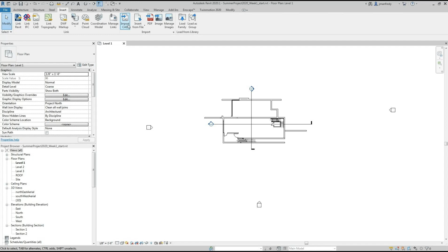Okay? So when you click Import CAD, it'll insert a CAD drawing into Revit, but you do not want that to happen, because data from Revit and AutoCAD will be mingled in the same project file. It does some unnecessary things to Revit. It brings a lot of garbage into Revit from AutoCAD, and you don't want that to happen. So what you should do is always link AutoCAD into Revit. Okay, so let's do that.